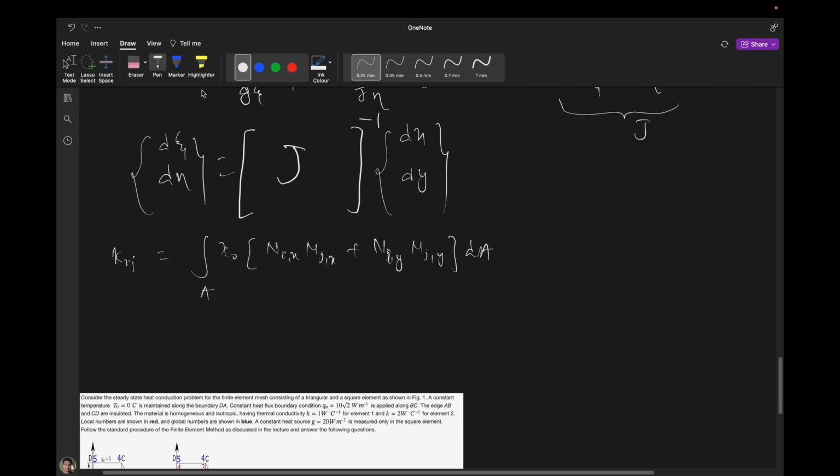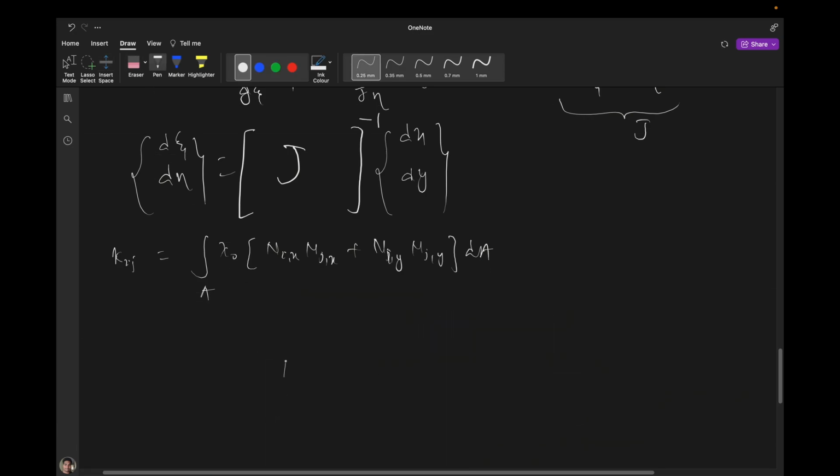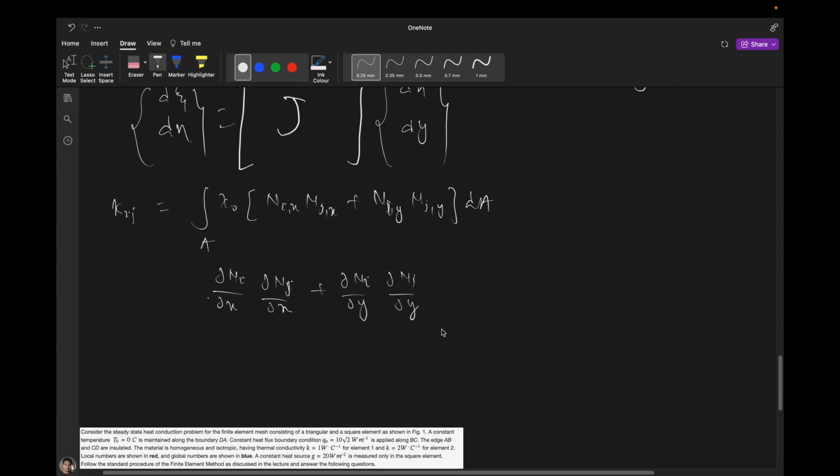Okay, and this n_ix n_jx is nothing but del n_i by del x del n_j by del x plus del n_i by del y del n_j by del y, and it is nothing but the gradient